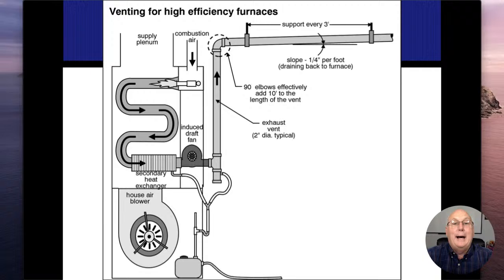So now we get into the high efficiency furnaces. And each one of these things are different. And you do have to look at the manufacturer's venting instructions, and depending on the size that they're going to be is how long of a run that you could have. Now, when we're dealing with the high efficiency ones, very rarely do I ever see these things have a problem.